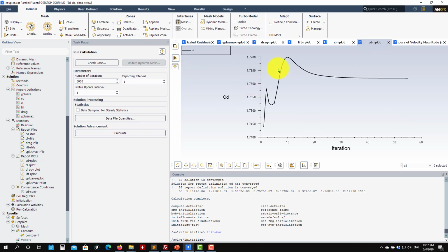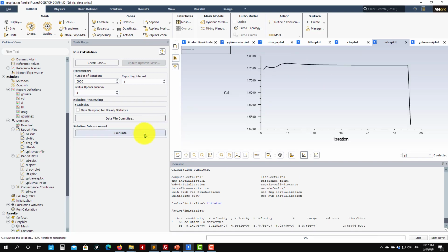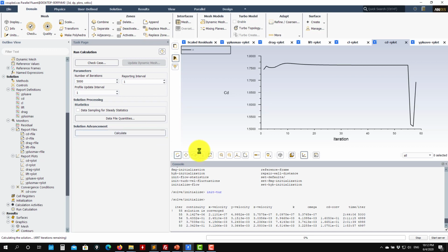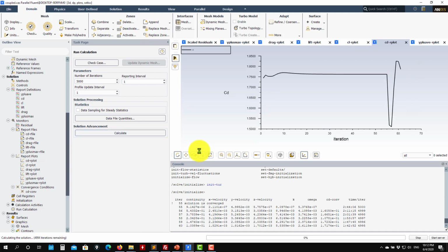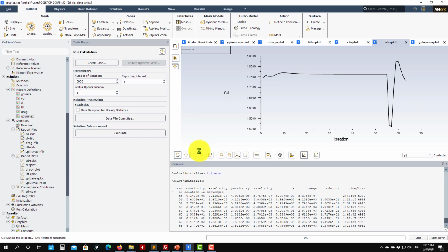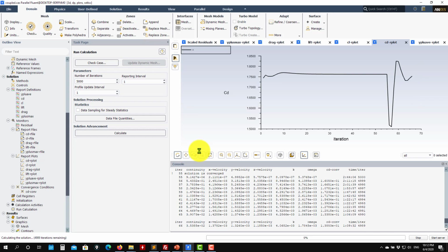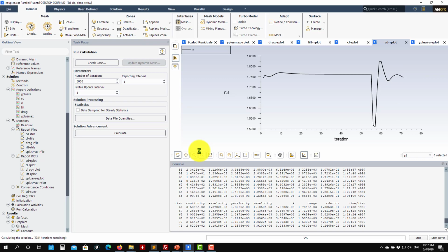Okay, so also pay attention that these are our residuals, our quantities of interest. I'm converting like this, and let's see what we're going to have now. Okay, I press. So we see that jump. And let's see what we have now with this SIMPLE solver. So something that you might notice right away is that the cost per iteration is lower. It's much faster. And as you start to monitor memory, you also will realize that it uses less memory.